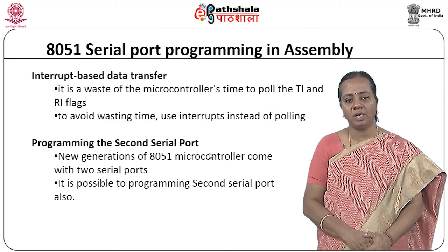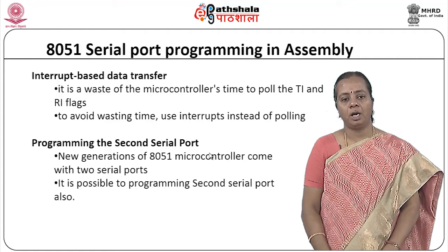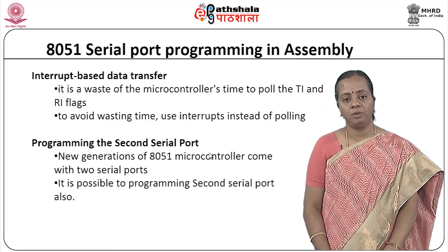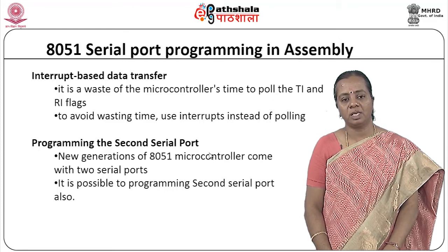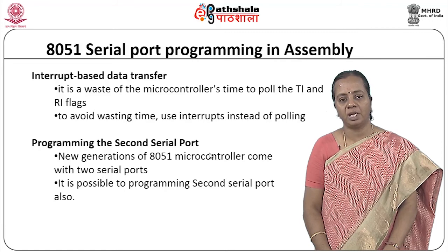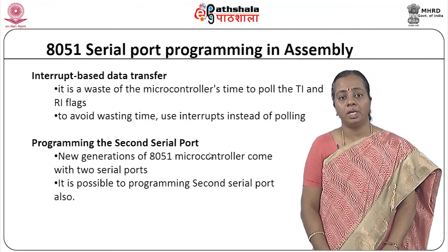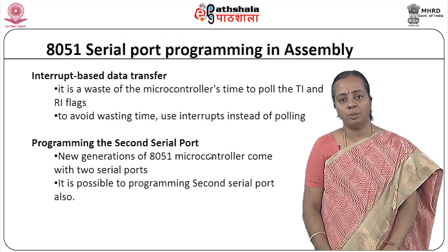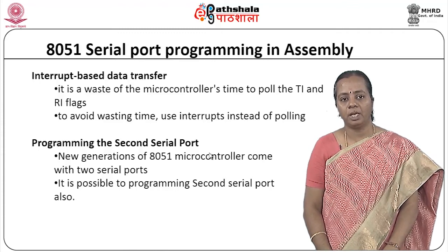Now we have only one set of RX and TX port. In the next generation we will have another set of serial ports. So with 2 sets of serial ports as well as interrupt based data transfer, serial communication will be improved much better in 8051.